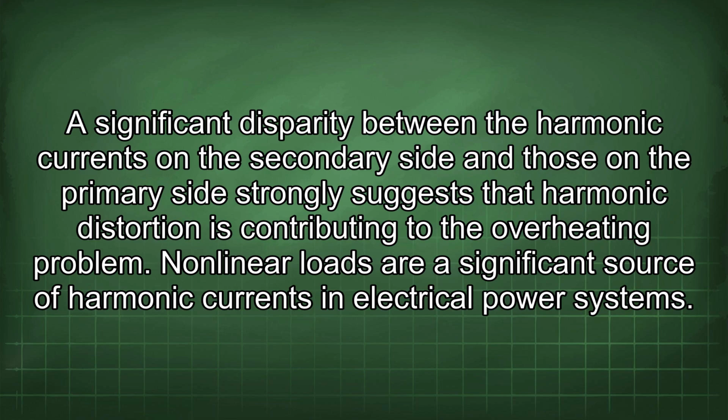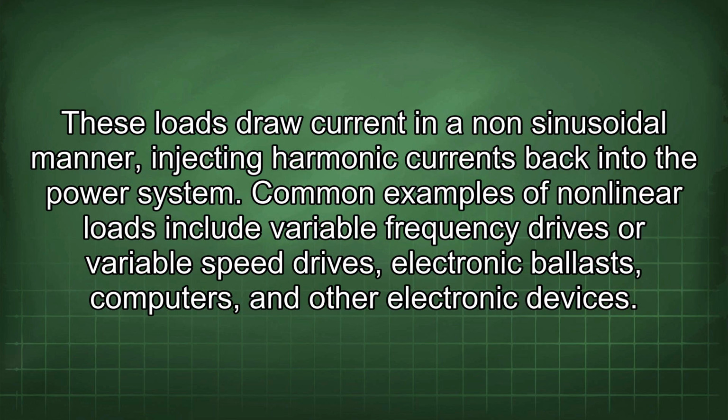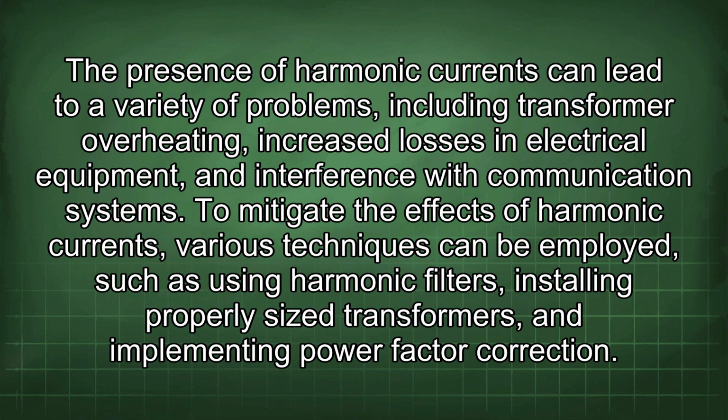Nonlinear loads are a significant source of harmonic currents in electrical power systems. These loads draw current in a non-sinusoidal manner, injecting harmonic currents back into the power system. Common examples of nonlinear loads include variable frequency drives or variable speed drives, electronic ballasts, computers, and other electronic devices. The presence of harmonic currents can lead to a variety of problems, including transformer overheating, increased losses in electrical equipment, and interference with communication systems.